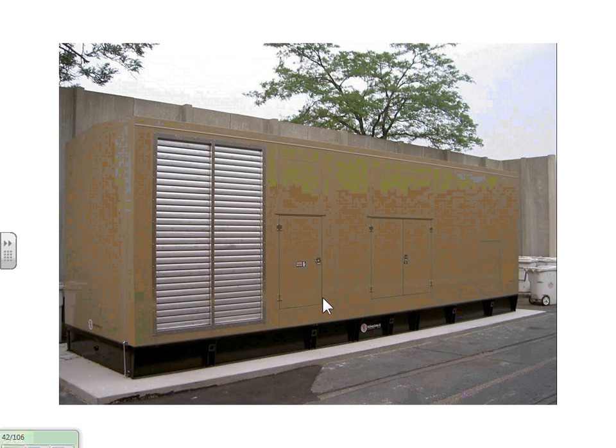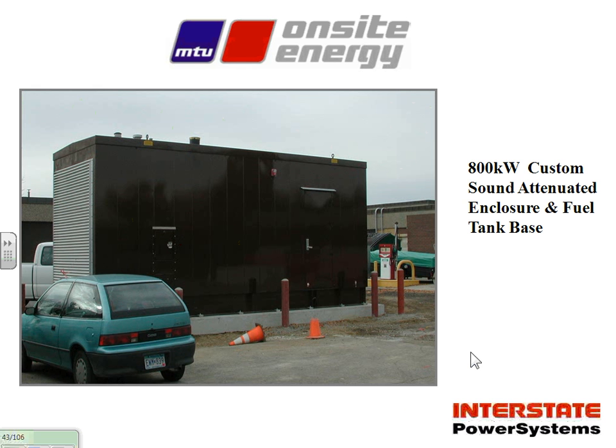And we have those on each end, both on the inlet and the outlet. So this is also a very quiet design. Again, it's probably a 12-hour tank due to the height. I think this one's like a 1,500 kilowatt set. This one's at a hospital in Hutchinson. Same kind of thing. It's a sound attenuated enclosure with the base tank. Very common.